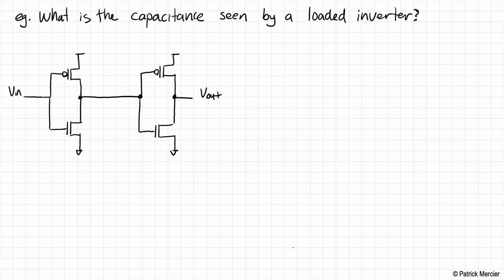Now, because we're dealing with real MOSFETs here, we now have to deal with the parasitic capacitance that we might see all over the various MOSFETs. I'll put my solder balls here to make things extra clear. Okay, and so what do I mean by that? Well, all of these transistors have parasitic capacitance everywhere. And what we'd like to do is represent that parasitic capacitance by some one overall load capacitance. We'll call this CL.